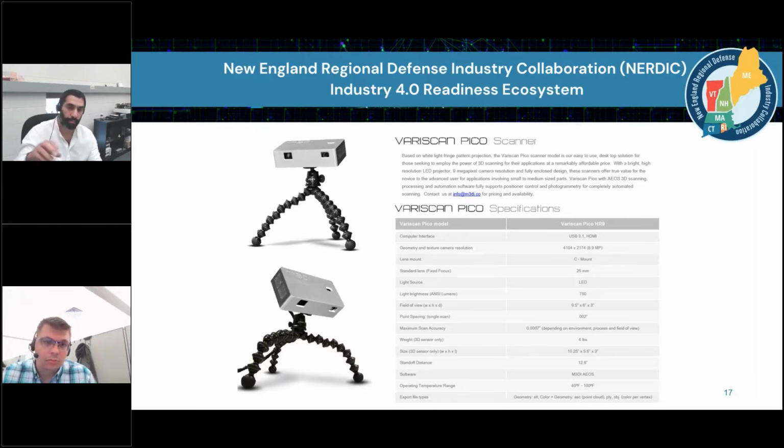In this case, picking up, as an example, this particular sensor and then moving it around the part to be able to scan it and determine where you need to make some corrective actions. And so in this case, if we were to use a collaborative robot that had a 5 kilogram payload, this particular sensor is 4 pounds, so it's close to 2.5 kilograms. So you can start to see how quickly you can take up some of the weight capacity that the robot can handle. Next slide.